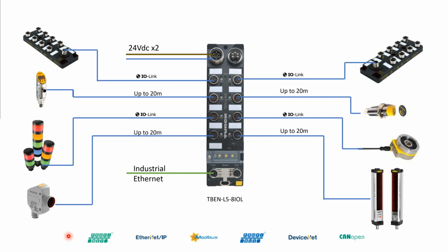This block in my left hand is just a 16 discrete IO block. Any point's an input, any point's an output, with its own IP address. And then this one has 4 analog signals. So in this application, you would have 2 different devices to purchase and mount, 2 different IP addresses, which again, not a big deal sometimes, but sometimes the cost and the extra mounting might turn you off the application.